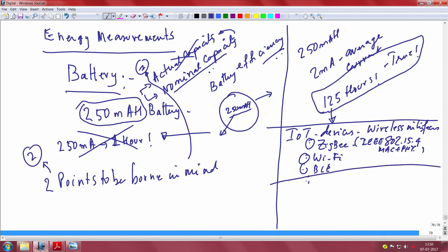talk about the wide area low power, which has LoRa WAN protocol, LP WAN as they are called, low power wide area network protocols, which are technologies which are LoRa, you have Sigfox, then you have NB-IoT, right. You also have LTE-M. We mentioned this, but I will just recap that these are all possibilities for the LP WAN for beyond the access devices, but more the gateway.